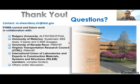And other people, I know Ramiz and others like Hamid Bazin, have tried to come up with smaller scale tests that use a smaller quantity of binder, apply fracture mechanics, and ideally we could run multiple dimensions or ligament lengths, and therefore apply a full-blown fracture mechanics approach and come up with a parameter that is not sensitive to the specimen geometry. That would be ideal.